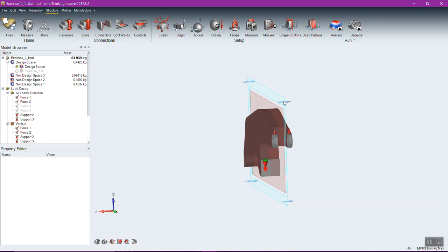Extrusion is a method in which we take a liquid or a semi-liquid and we push it through a shape so it extrudes out into a shape. If you ever had a Play-Doh toy when you were a kid, where you put the Play-Doh into a little bucket, and you put a little shape in front of it, and you push down on the handle, it puts out little triangles or diamonds or new shapes. That's extrusion. Well, extrusion means you have to have a continual cross-section all the way through, because you're just pushing it through a shape, and each subsequent cross-section is exactly the same.